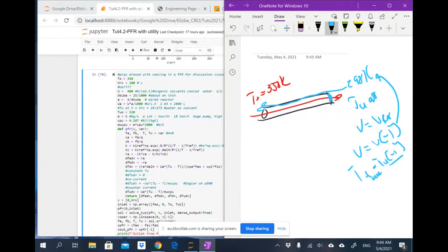Okay, at that last integration step, it must be 298. And I am going to change my boundary condition for TU where V is equal to 0. I am going to play around with that, and my first guess is TU naught equal to, and I just guessed there, the value of 320 Kelvin. And then I ran it.